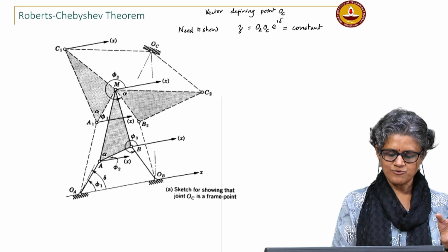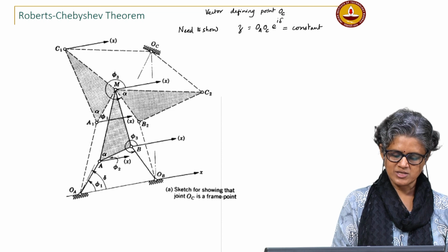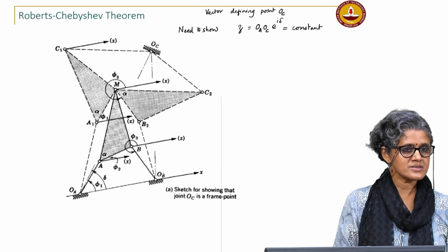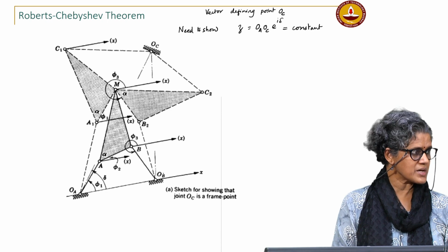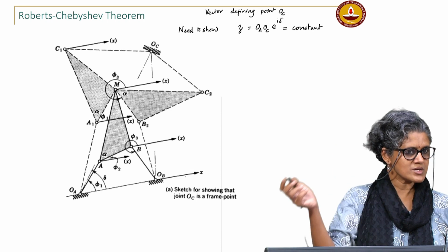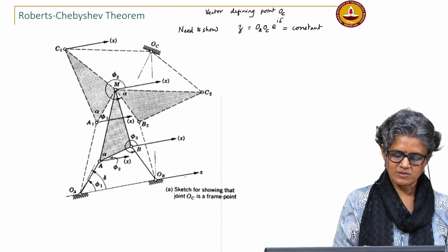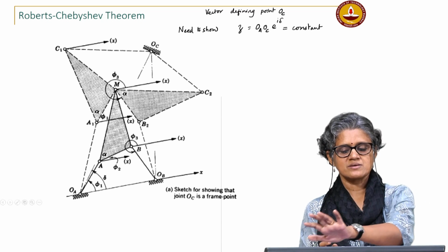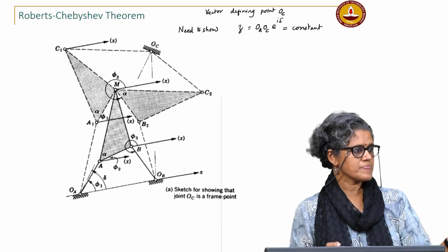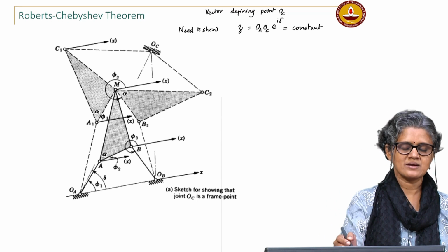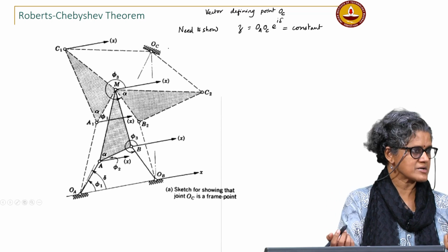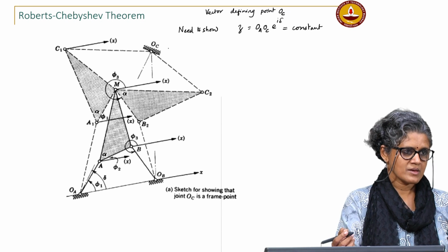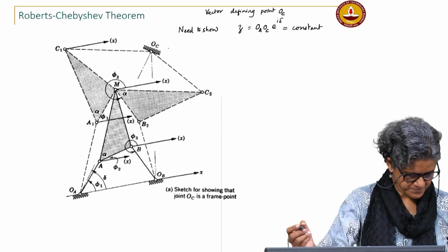Okay, phi 1, phi 2, phi 3, that is the notation that is used here. It should be independent of those 3 angles, which are the angles of the 4 bar, our usual theta 2, theta 3, theta 4. If it is independent, which means as the linkage moves, this vector remains constant, then you have established that I might as well make it a fixed pivot, without any issues.